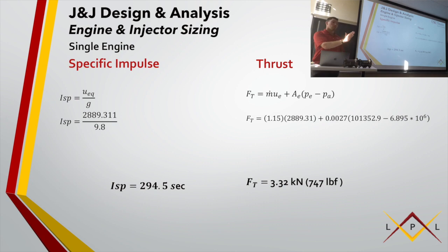There is a shock or an expansion fan depending on what your area relation is, right? Because it has to do with the pressure differential. We just said the optimum is where PE equals PA. So we're saying the exit of your nozzle equals out there, so there's no pressure differential, so there won't be a shock. That's why it's the best, because there's no shock, there's no energy loss. It's perfect, right? It just comes out there and now it's just chilling with the ambient. So that's where PE equals PA.